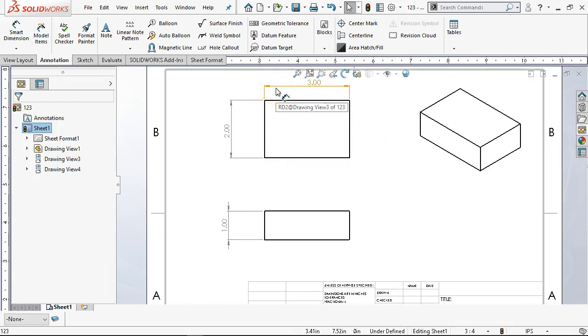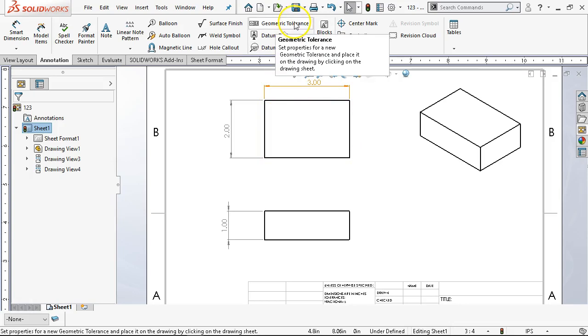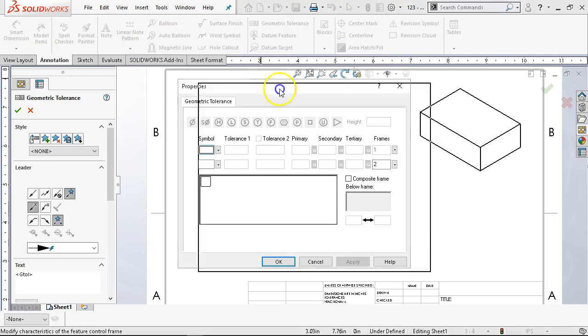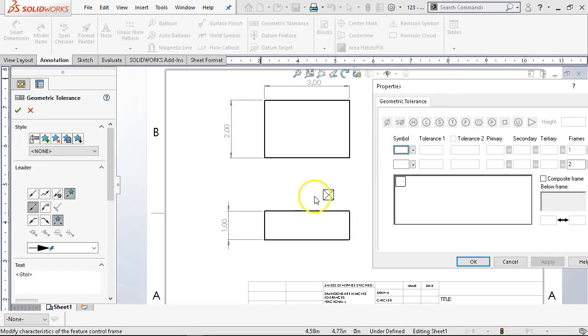So no datum feature is established. So we do want a geometric tolerance, and the choices are we can place it in relation to a surface. So this top surface is our biggest area. When we set it down on the surface plate, it's going to provide us with the greatest stability. If I set this edge as flatness and this side is parallel, I'm losing some of that stability. I'm not going to be able to have the same types of measurement.